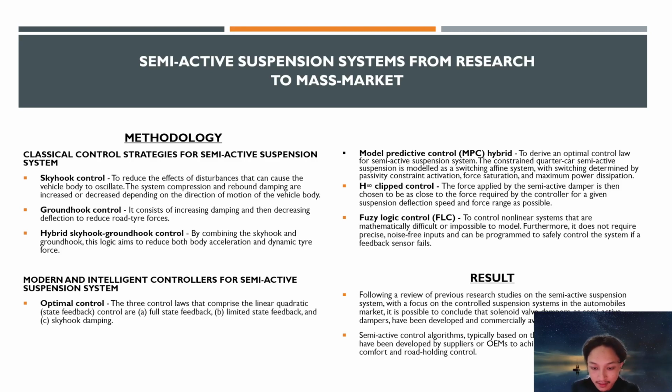Following the review of previous research studies on the semi-active suspension system with a focus on the control of suspension systems in the automobile market, it is possible to conclude that solenoid valve dampers as semi-active dampers have been developed and are commercially available. Semi-active control algorithms, typically based on the skyhook control strategy, have been developed by suppliers or OEMs to achieve the proper balance of ride comfort and road holding controls.